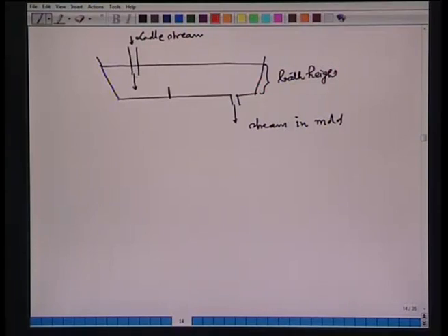If I put a dam which obstructs the flow, imagine now the liquid is flowing, hits the bottom, then it will go here, and from here it will be surface directed, and then it will mix here, here, here, and ultimately leaves the tundish nozzle.